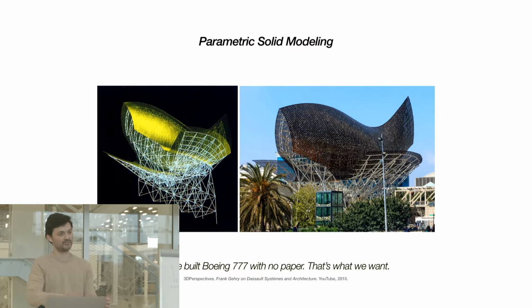So you can start with simple 2D sketches and then evolve from this. You say the first level would be a 2D arc, and then you can extrude it, and then you say it should have a certain number of divisions, and on the third division it should continue flat or whatever. So you evolve it from a simple sketch towards a fully built model. And you can constrain things, for example: a certain line should always be parallel to the ground, or should always be at a 15 degree angle to the ground, and stuff like that.